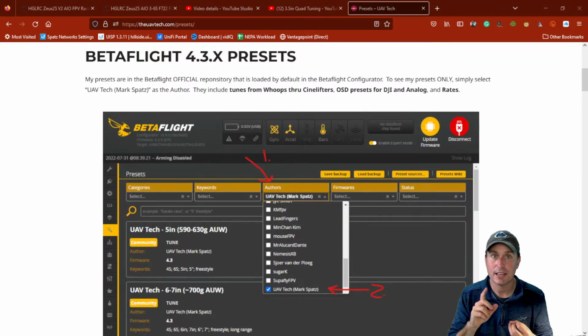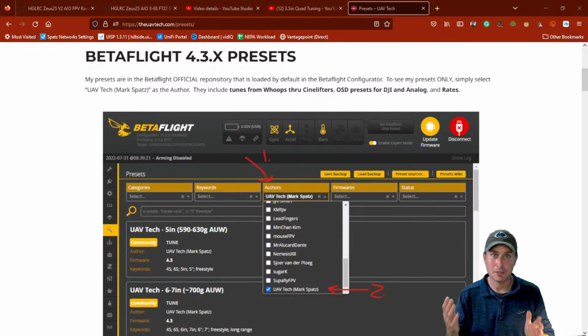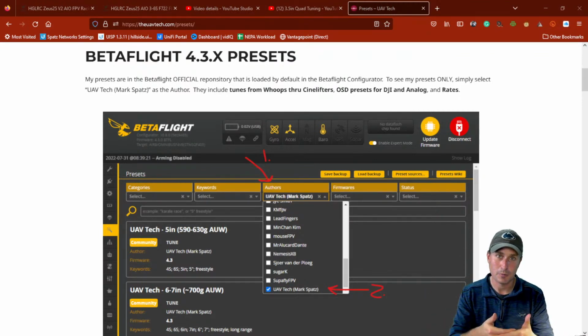You may note that the battery life is less. I doubt it though. Not on 1404 motors you won't. Maybe on a whoop, and even on the whoops, I didn't really notice anything between 48 and 96. So I don't ever run 96, but take note of it. If you do notice the battery life, then you have to make a choice, go with 48 or 96. If you don't notice any battery life difference and it's fine on 48, then stick with 48. Obviously, if it solves your issue, then you're done.